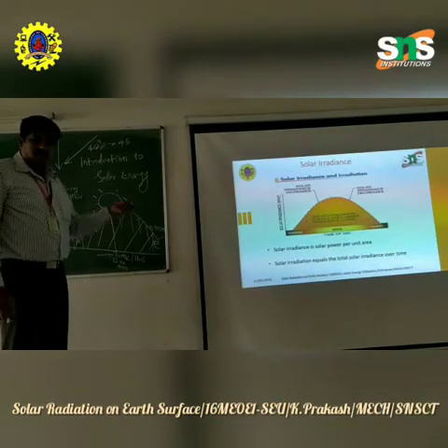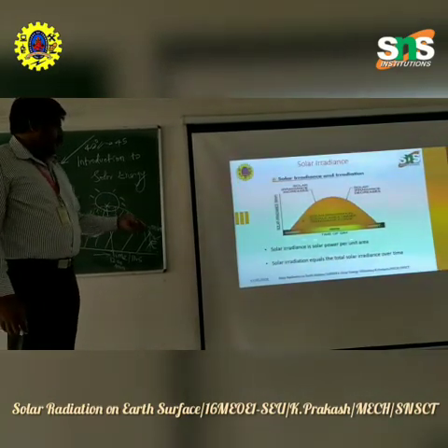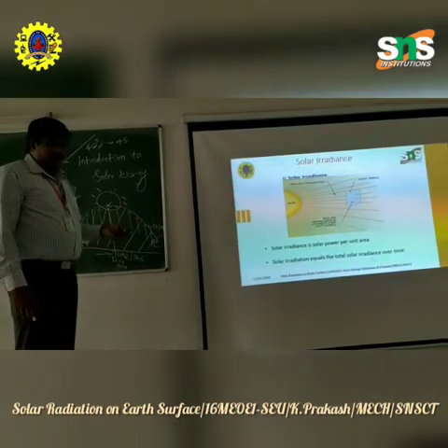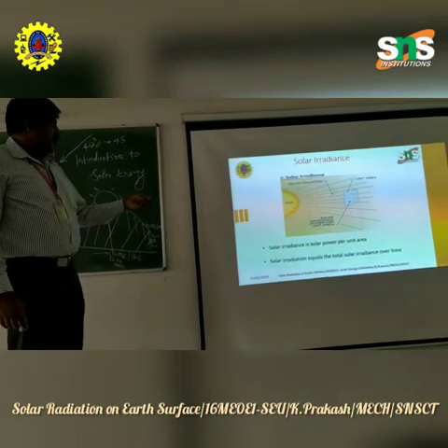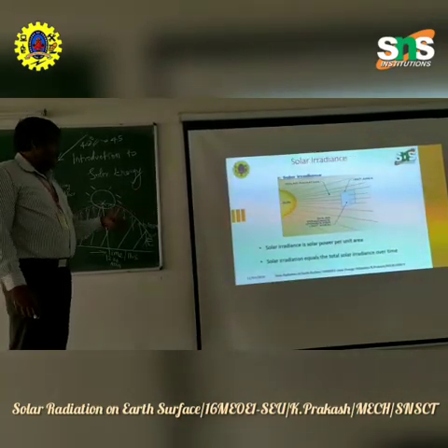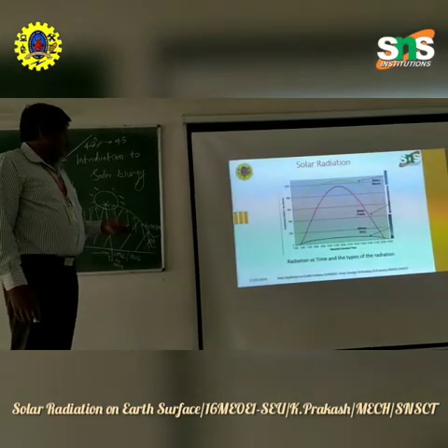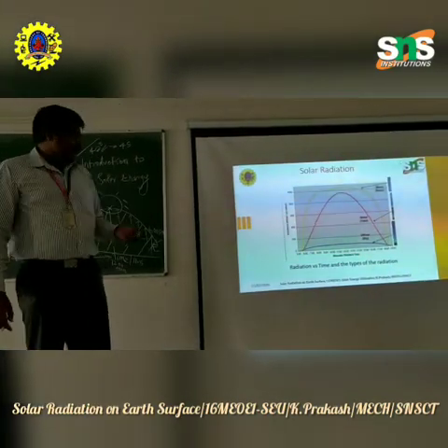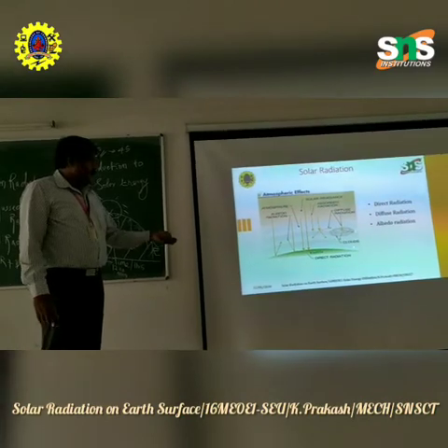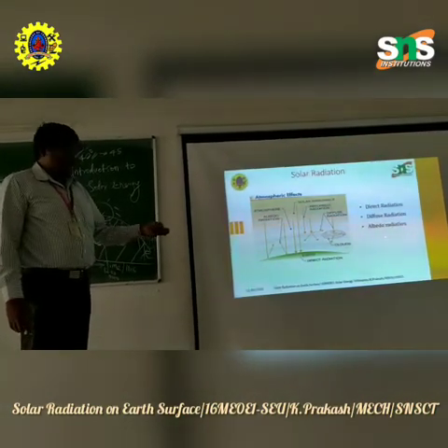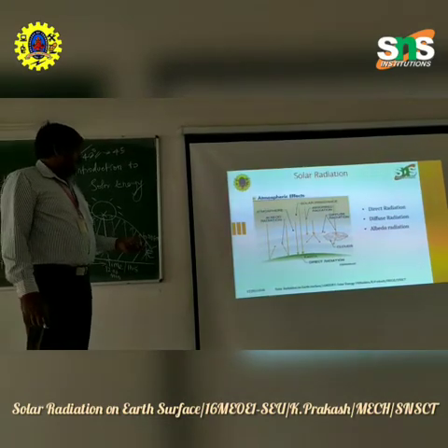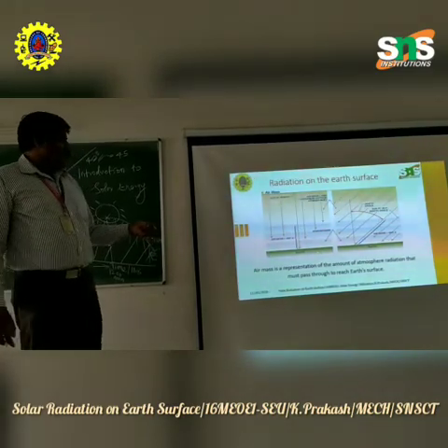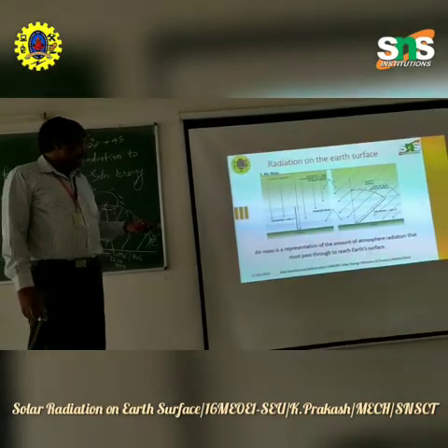And we discussed what solar irradiance is, and made a comparison of time and solar irradiation. We also did a small possible experiment to measure the solar radiation. We discussed the graphical representation of the solar radiation falling, and the types of solar radiation: direct, diffuse and albedo radiations. And we discussed the air mass, how the air mass varies and how the zenith angle is obtained.